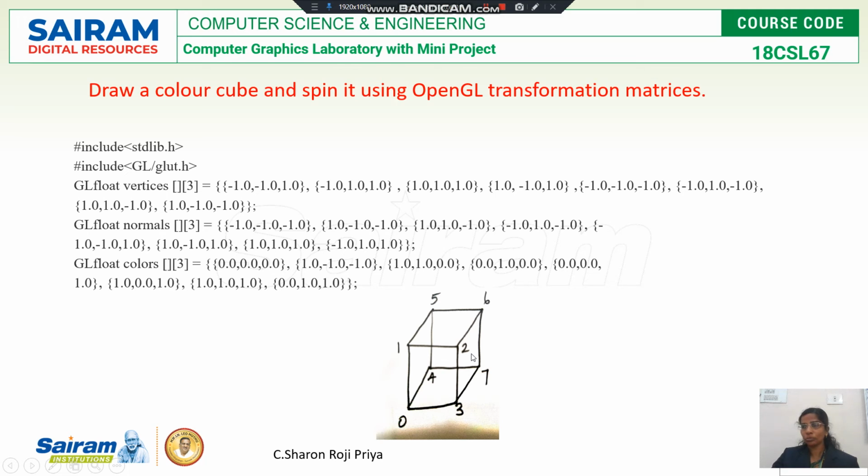Assume this is a cuboid, and hope you can see. Assume this is my front view. If I am looking at the front side, the back side is exactly behind this front face. So if front is visible, back is invisible. Take this side, this is my left side.